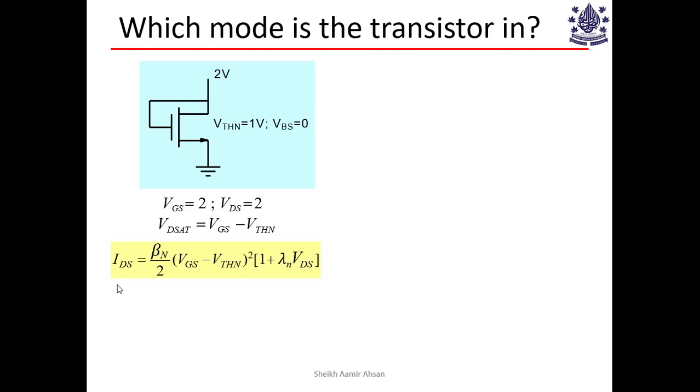So this is the typical expression for saturation, right? But one thing, how this one becomes more interesting is because we already have shorted gate and drain together, so this equation will be more useful under this condition. VGS can simply be replaced by Vx because now it's not a 3-terminal device or a 4-terminal device. It's actually a 2-terminal device, right? Where gate and drain act like one terminal, source and body act like another terminal.